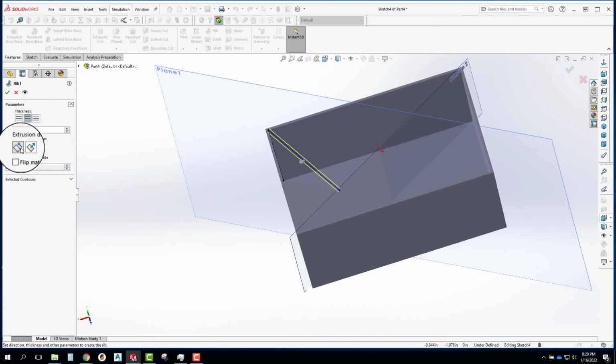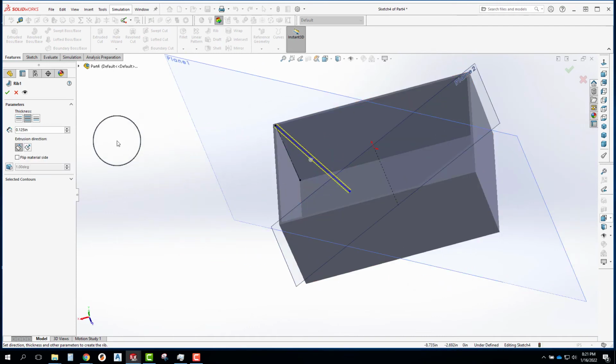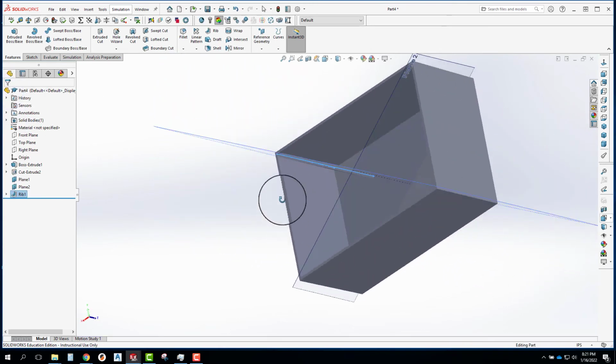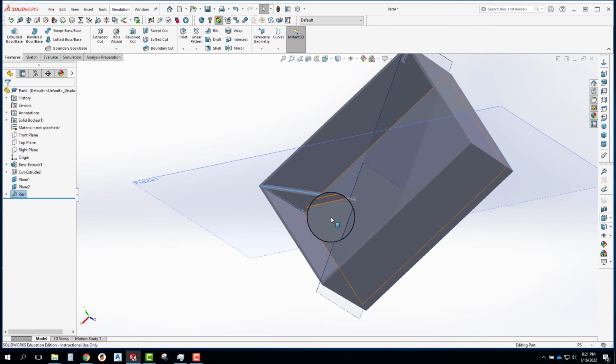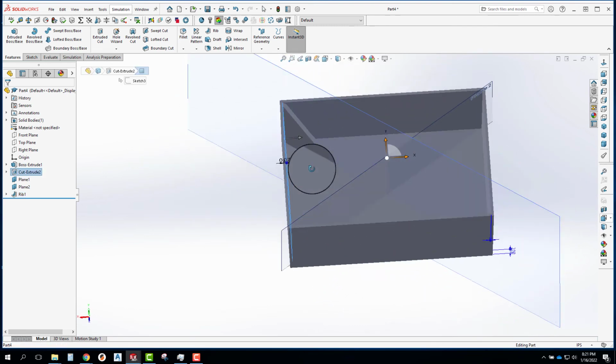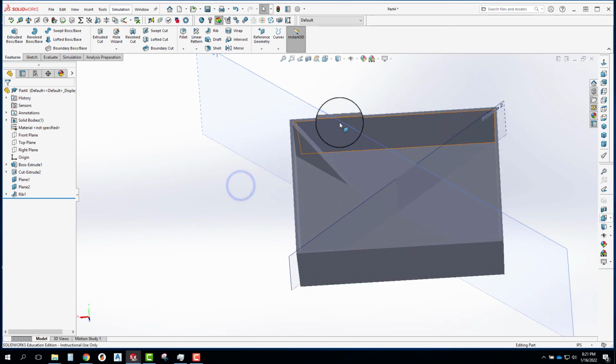And you can see here which direction it's going, and see the arrow. The arrow looks like it's going the direction I want it to. So I'll just say make that rib, and you can see it added in a rib that went right up to the bottom and right up to the sides there. So that's one way I can create the rib if I want something diagonal like that.